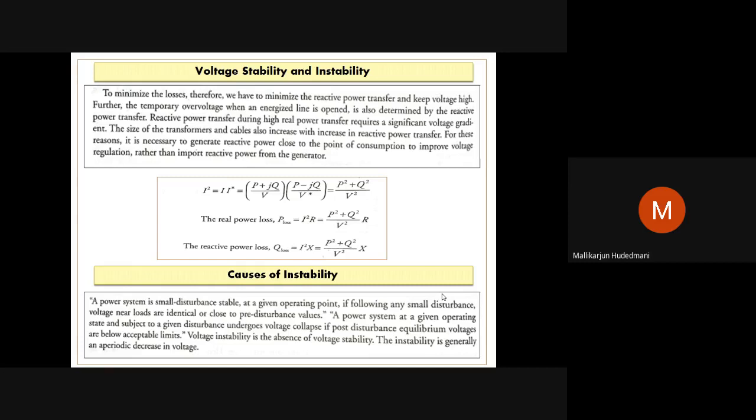To overcome this, a study must be performed. The stability aspect must be worked out, and stability analysis reveals what is needed, when, how much, and where it needs to be. So this study has to be performed as stability analysis. On stability, we have so many parameters, short term, medium, long term, depending upon the system's operational scope, and they must be worked out. Basically for us, the system's inherent inability or lack of control, lack of reactive power subsequently, or anything which makes it unable, is the reason for instability.